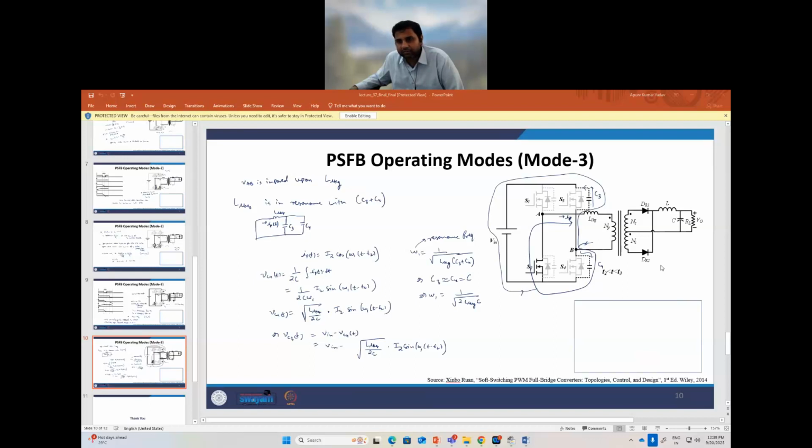A 1 kilowatt load is pretty much... with 3.3 kilowatt, you have a good amount of fundamental component of current. As per EV standards, it comes under level two charging. The peak value of current will come somewhere around 20 amperes, and the RMS is 14 or 15 amperes.